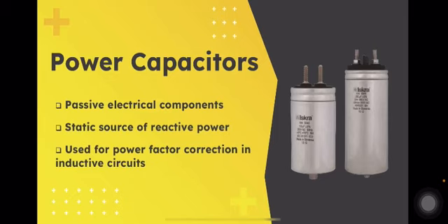So, what is a power capacitor? A power capacitor is a device that stores energy within an electric field. This can be achieved by having two oppositely charged electrical conductors separated by dielectric materials. Power capacitors are constructed from several smaller capacitors commonly referred to as elements, windings, or packs. Elements are connected in series based on the rated voltage and in parallel based on the required kVAR.